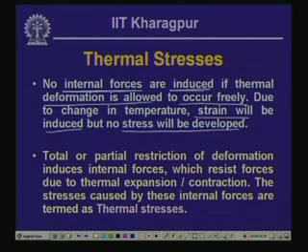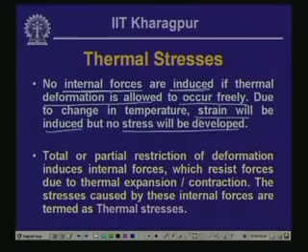So, naturally there will not be any stresses, but since it is undergoing deformation, either it is expanding because of a rise in temperature, or it is contracting because of a decrease in temperature. So, there is movement, there is deformation, and in turn there are strains, but since the movement of the body is not restricted, no internal forces are getting generated, and hence there will not be any stresses in the member. That is why strain will be induced, but no stress will be developed.